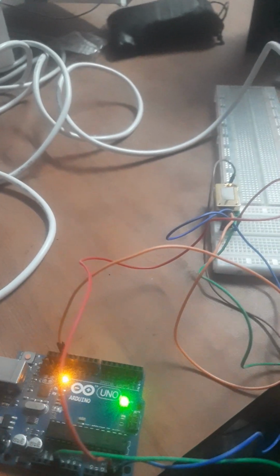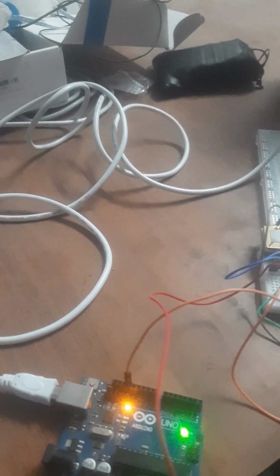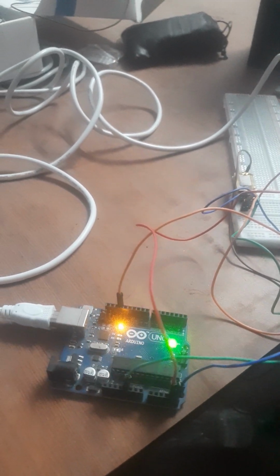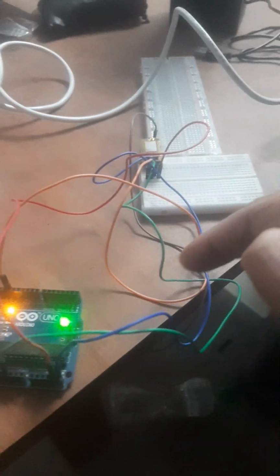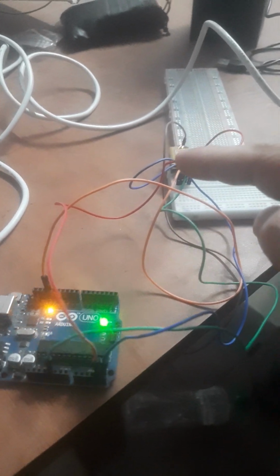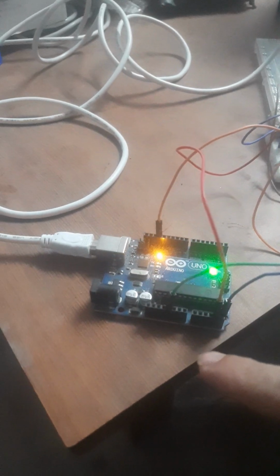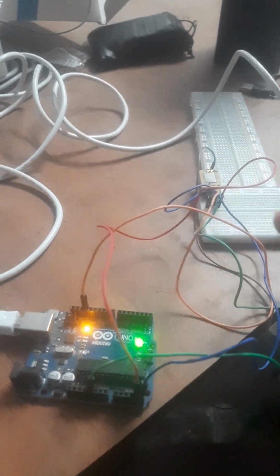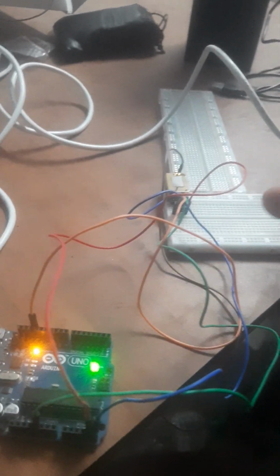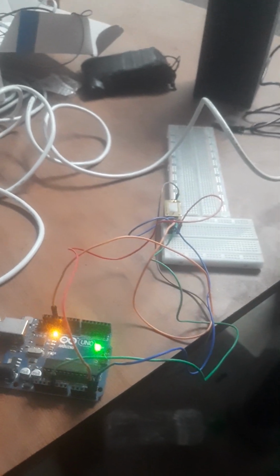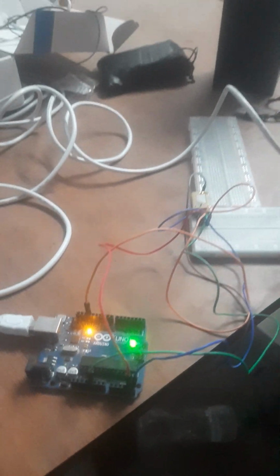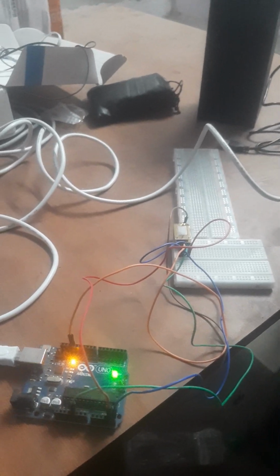Ground and the 5 volt supply are the other pins. SCL is connected to A5, as I told you earlier. The third one, the brownish orangish wire, goes to the ground, and the blue wire is as I told you earlier. The green wire, the last one, is giving the 5 volt supply. Under these conditions the inbuilt pull-up resistors work very well and don't make the current go too high to spoil the devices inside.